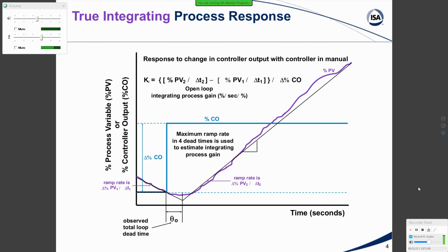I did some calculations, based on physical principles, and found that for that particular incinerator, the pressure could ramp off scale in 1/4 second, which explained a lot of the problems we were seeing. So anyway, there's a large diversity of ramp rates. Often the ones we see, though, for temperature and for composition other than pH, the ramp rates are quite slow.